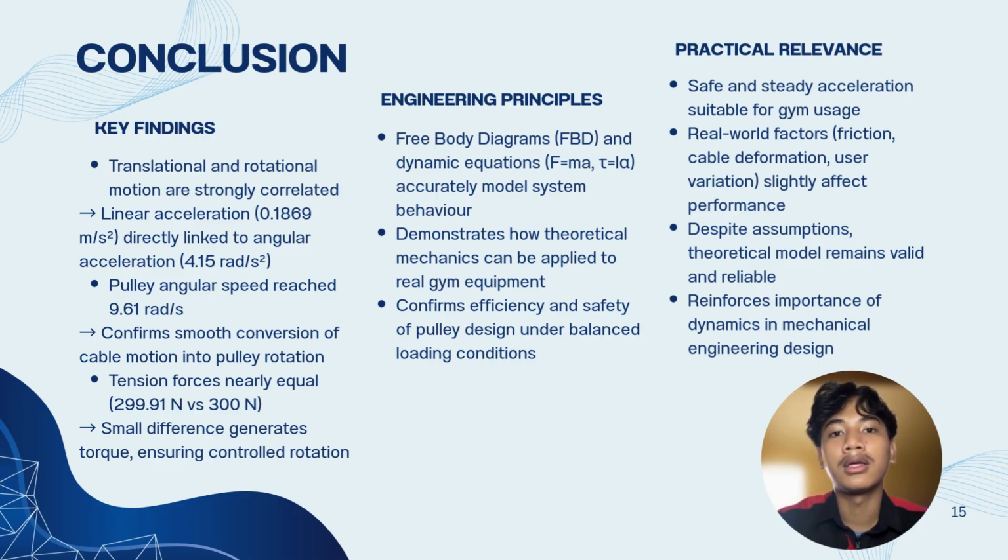The study confirmed that free body diagrams and dynamic equations, F equal to ma and torque equal to inertia times angular acceleration, can accurately model system behavior, validating the efficiency and safety of the pulley design, while real-world factors such as friction and cable deformation may slightly affect performance. The theoretical model remains reliable. Overall, this case study demonstrates how dynamic principles translate into practical engineering applications, ensuring safe and effective gym equipment design.